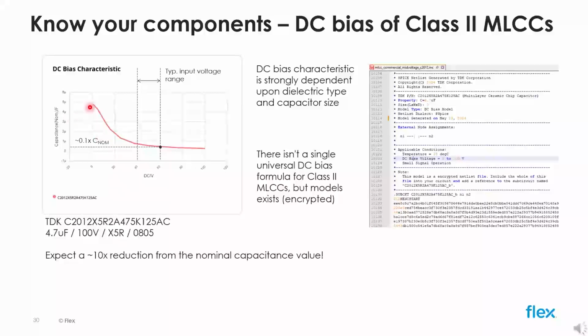Multi-layer ceramic capacitors can operate over a wide frequency bandwidth and are excellent components for an EMI filter. The high capacitance value necessary for an EMI filter usually precludes the use of class 1 capacitors, also known as NP0 or C0G dielectric, with vanishingly small dependence upon temperature or applied voltage. Class 2 capacitors have much higher capacitance per unit volume, but are also less linear with temperature. Most importantly, their capacitance is AC and DC voltage dependent.